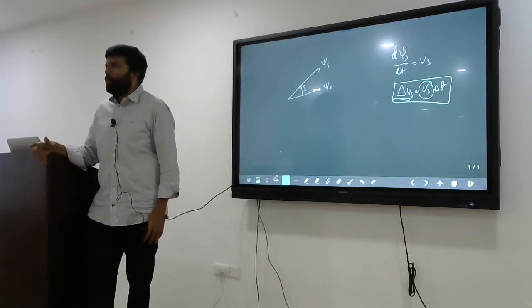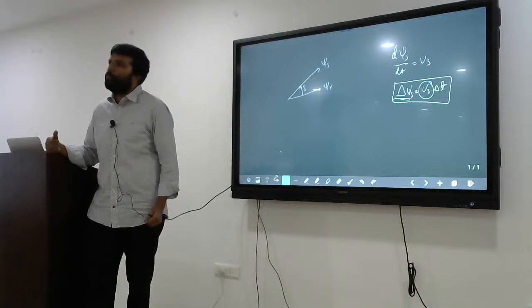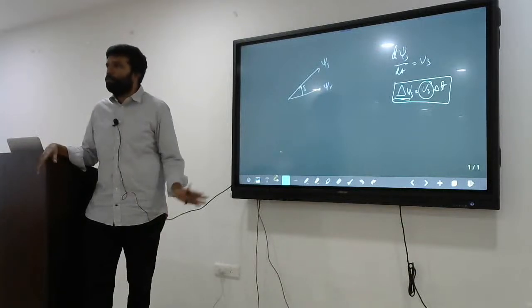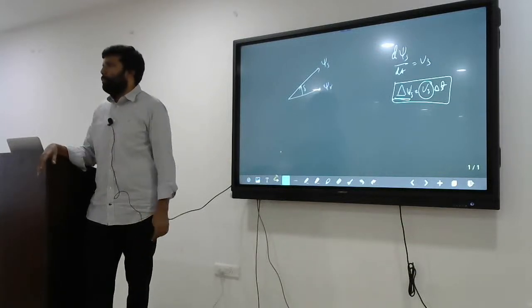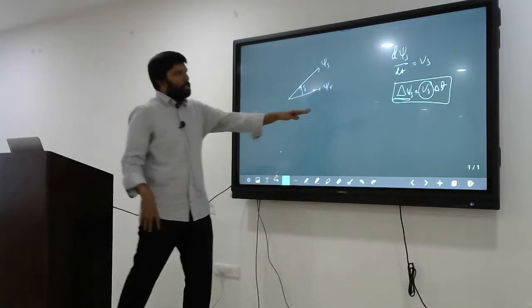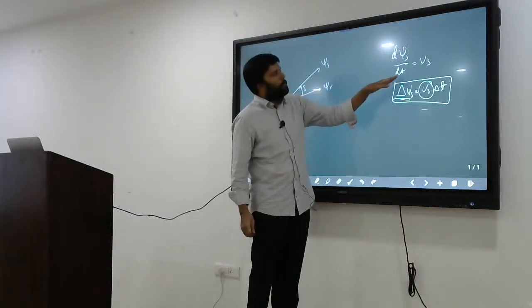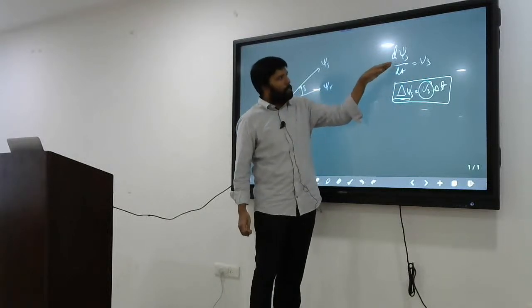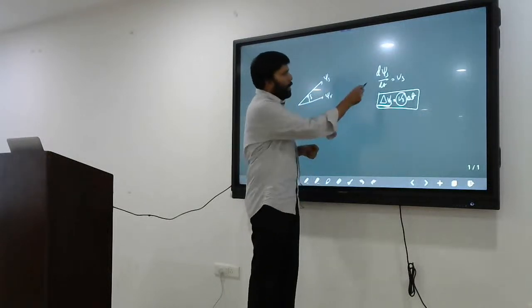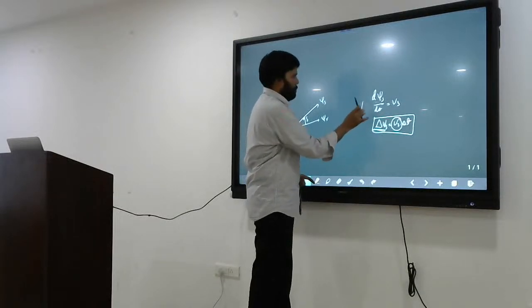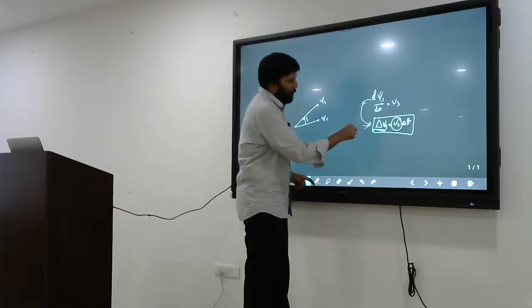See, in case of induction motor, please try to understand, you don't have any freedom on the rotor flux. But the stator flux we can control effectively. Stator flux we can control through the stator voltage, right? So this is the standard mathematical expression, d psi s by dt equal to Vs, the supply voltage, the resultant voltage. So from this expression, we can rewrite it like this.